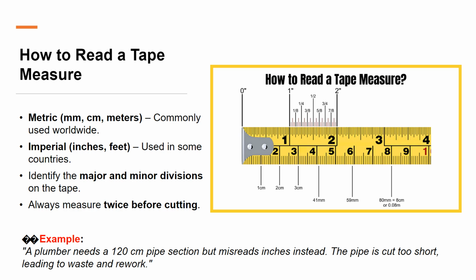Third, measure twice, cut once. Before cutting, always measure at least twice. Confirm your start and end points. Don't round off unless instructed. And if you're working with fittings, remember to include the fitting allowance.